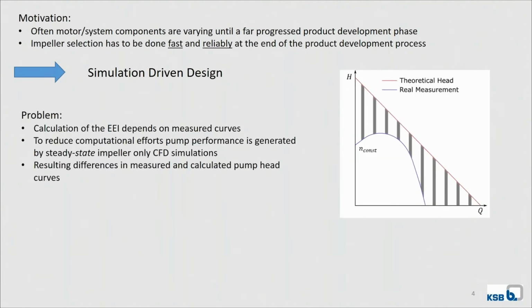The problems are the calculation of the EEI depends on measured curves. Yeah, this is one thing. Then to reduce the computational effort, pump performance is generated by steady-state impeller-only CFD simulations. And this results in differences between measured and calculated pump head curve. You see it here exemplarily on the right-hand side. Yeah, the gray area. This is missing information because